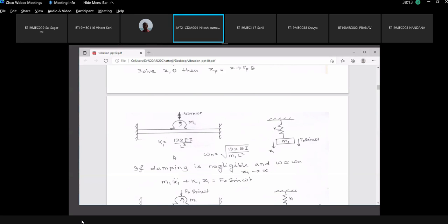एक गड़बड़ कर रहे हो. Power can be different. A motor can be designed for different power. Remember that. If you go to the market, generally वो fractional horsepower बोलता है उसको. घर का अगर पानी उठाने के लिए पंप चलाना है, they are generally in terms of horsepower. You can have a variation in horsepower, but you cannot have a variation in RPM.